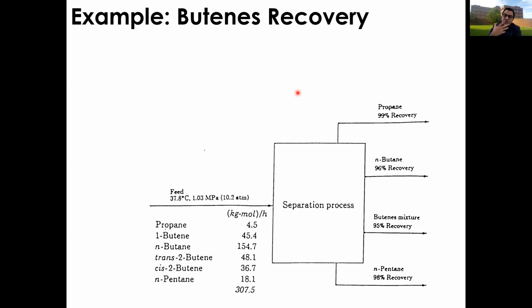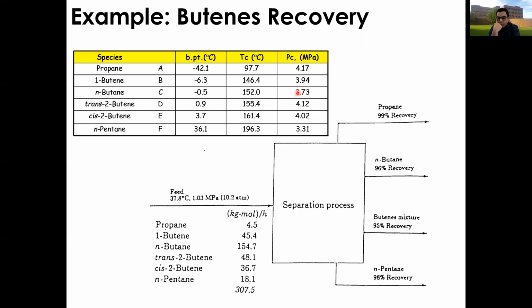So usually the first step you would do, intuitively, is get the boiling points. Which species out of these 6 is the easiest to just boil out? So again, first step, always look at your boiling points. Let's have a look at them. If I look here, I can see there's a big range.